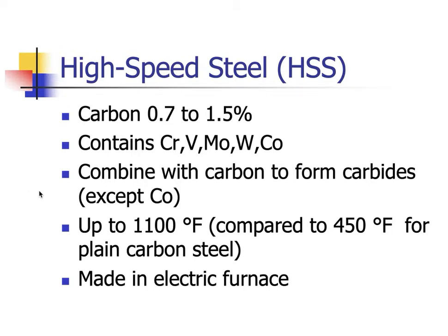You may have seen, if you buy a drill bit and you look on the side of the drill bit, if it's big enough, some of the small ones you can't read it, but if you look on the side of it, or if you look on the package, it might say HSS, or high-speed steel. And what that is, it's a group of alloys that are resistant to high temperature deformation. In other words, we're drilling something and you want that edge to stay hard, but remember that when you're drilling something, it builds up heat right where you're shearing that material off.